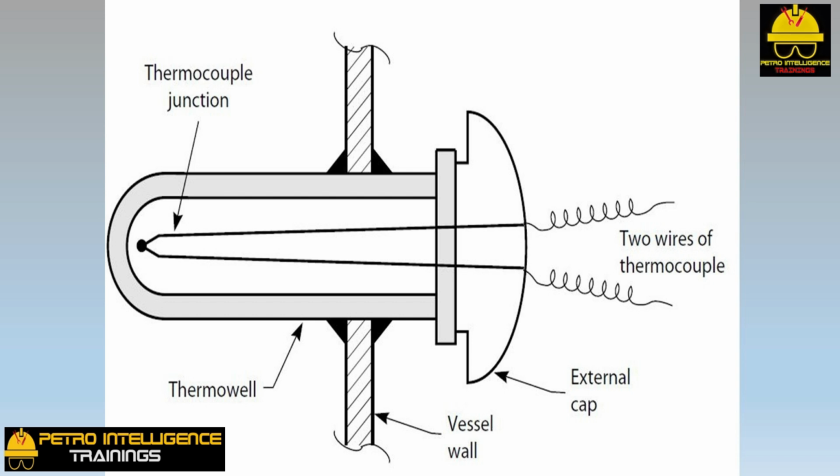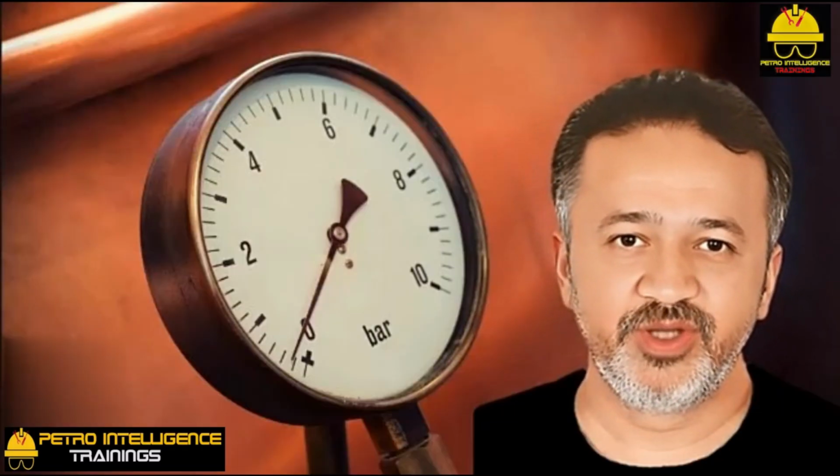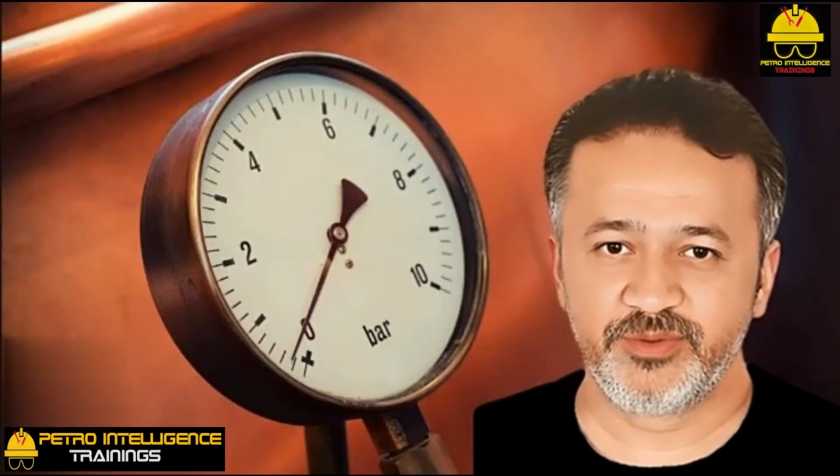It is not uncommon for a thermocouple, regardless of the type of junction, to generate too low a temperature signal. If the exterior of the thermowell becomes fouled, the indicated temperature, generated by the thermocouple, will drop. The problem is that the external cap of the thermowell assembly radiates a small amount of heat to the atmosphere. Normally, this has a negligible effect on the indicated temperature. However, when the process temperature is 600 to 800 degrees Fahrenheit, the thermowell is in a vapor phase, and the thermowell becomes coated with coke. I have seen the indicated temperature drop by 40 degrees Fahrenheit below its true value.